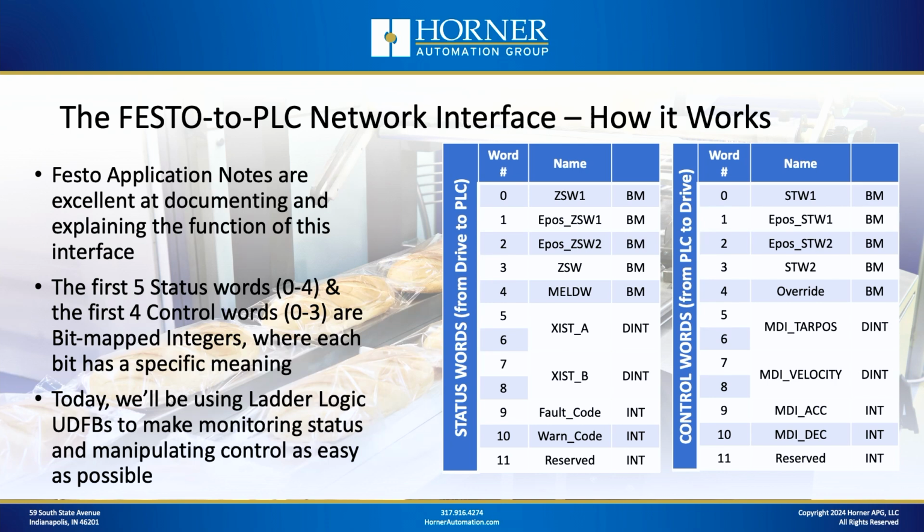The first 4 of the control words are bitmapped integers as well, so that you can effectively set the appropriate bits to make motion happen. But what we're trying to do with today's video and with these user-defined function blocks is to handle all of this status word and control word type interface through user-defined function blocks. So if you utilize those particular tools, it should pretty much take care of this for you.